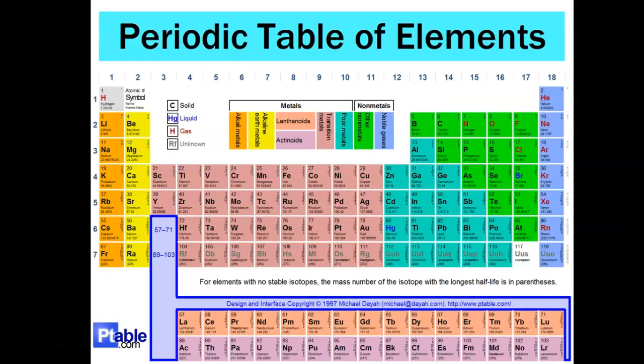So that's why we get by with using aluminum, even though it's got resistance out there. We get by with using it because we step the voltage up so high and the current goes down so low that the voltage drop on the line doesn't hurt.